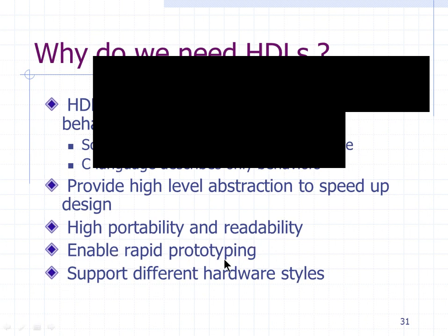Prototyping means we are creating samples or smaller models of our product or of our system. So we can quickly design using Verilog, implement it on an FPGA or some programmable device, build a small model of our system and test whether the system is working as per expectations or not. If it is not, we analyze where things are going wrong and fix it.